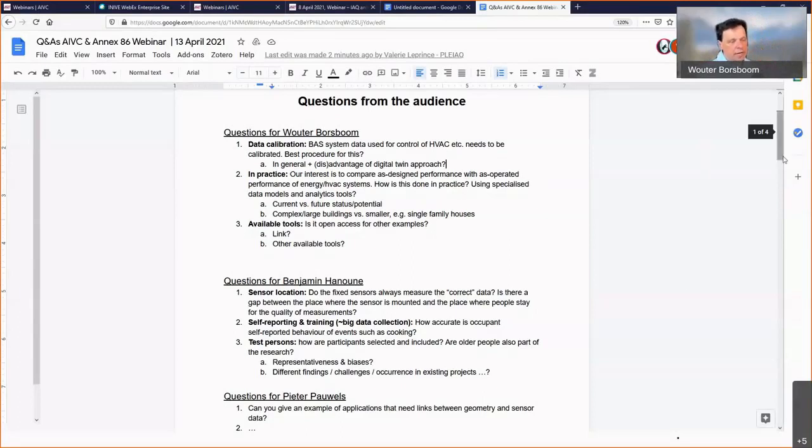But if you want to have, for instance, the COP value of the heat pump or the seasonal performance, or you want to look at the energy performance, those models can help assess the data. For instance, if you want to correct for the heating season or the cooling season, sorry, for the climate season. So first you train the model and then you calculate a reference year to look if the performance is met. And we've done that in the past.